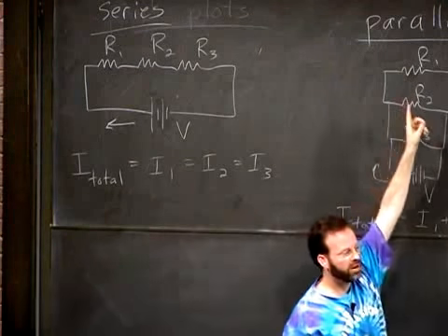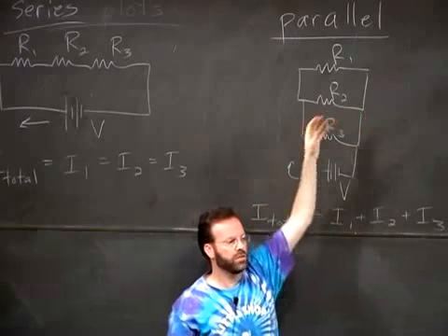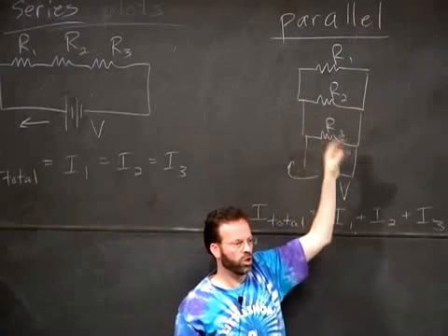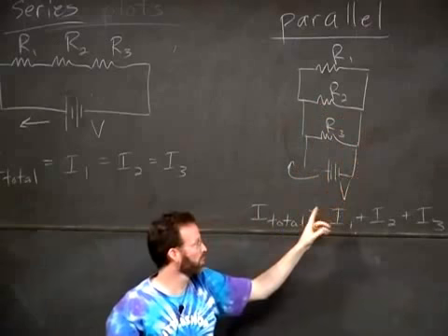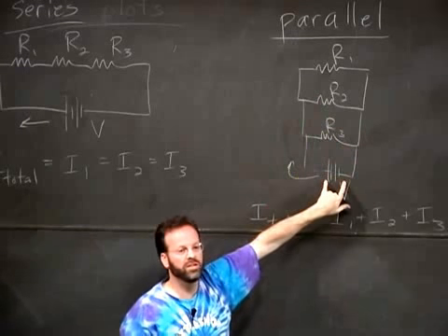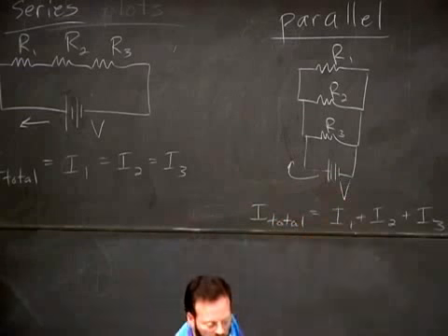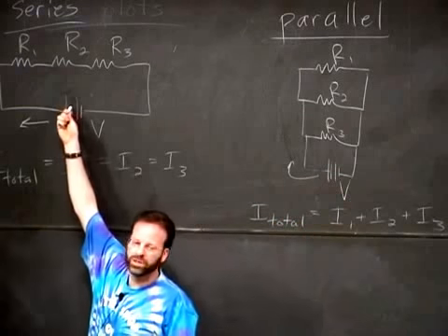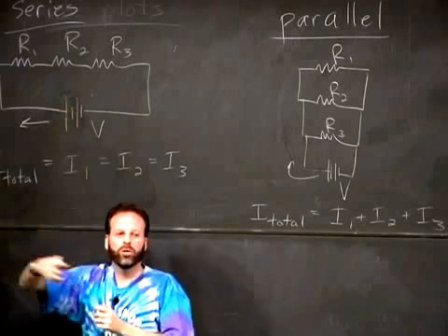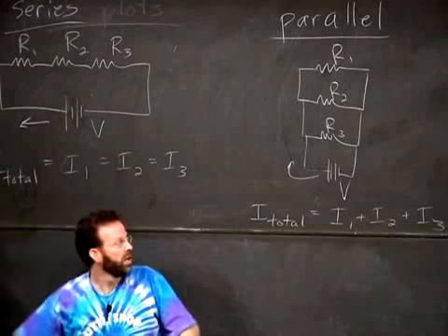Adding more resistors in parallel means there's more paths. They need current, and they each need it. So you've got to provide more current in the first place. The total resistance the voltage source sees would drop. Say that again. More resistors in series, it's got more to go through. Total resistance goes up, current goes down.